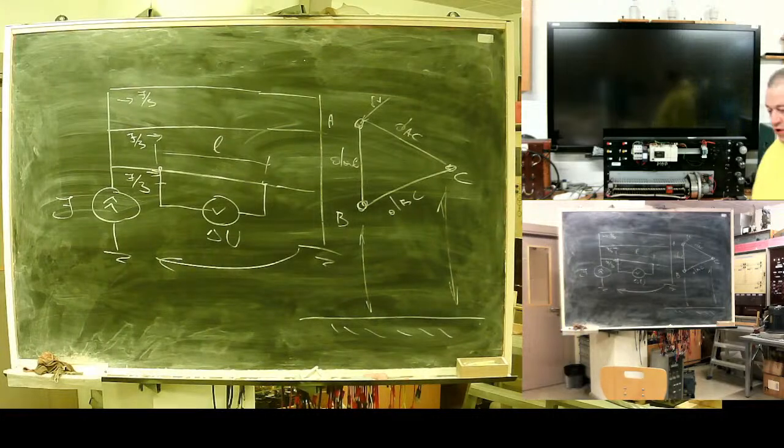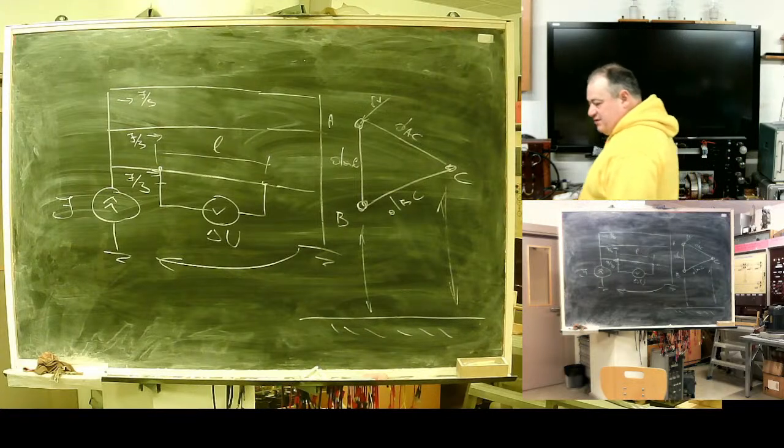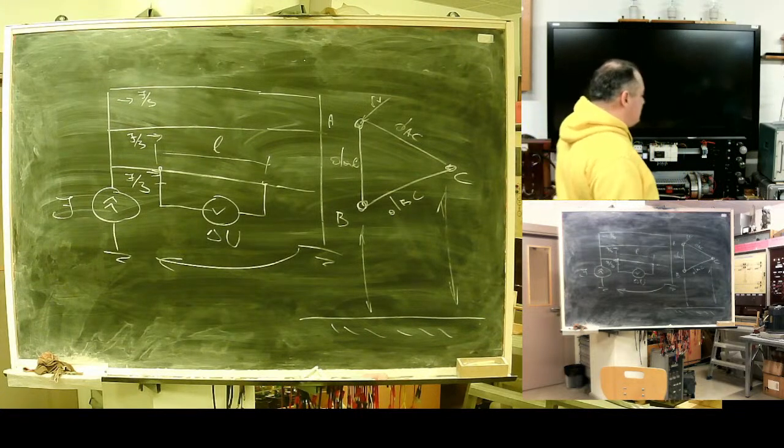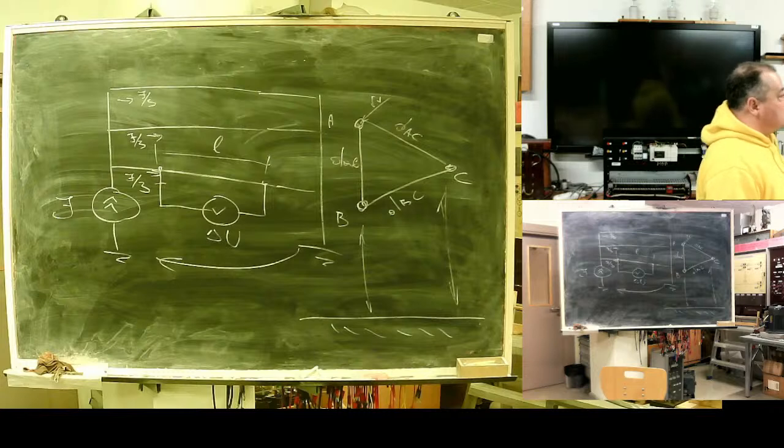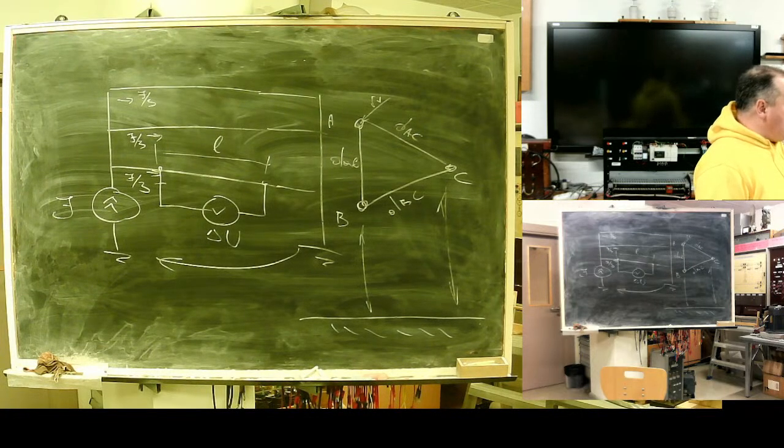The error from the assumption that we deal with a fully transposed line, when the line is in reality non-transposed, is somewhere from 5 to, in the worst case, around 9%.